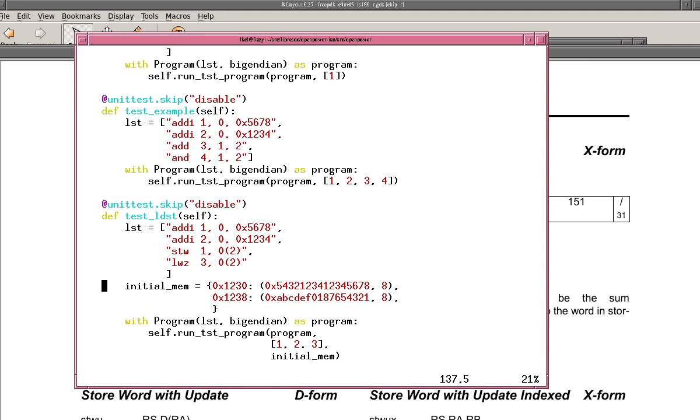all from Python. And then we do the exact same thing with the HDL. So we're doing this bootstrap process, which develops a very slow simulator in Python because it's easier to read and understand. Then we cross-reference and check it against QEMU by co-simulating our simulator versus QEMU.